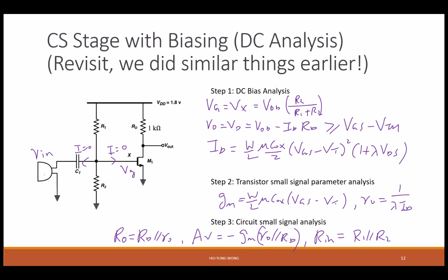How about the input impedance? We keep saying that it is infinite, right? But now is it infinity? When I come in, yeah, I see infinity here, but what else? You can go up and down. R1 parallel R2. So even at DC, you won't get infinity now because you need to bias the circuit. So in a real circuit, you won't get infinite input impedance. But that is the main point, the whole picture we have been doing now.